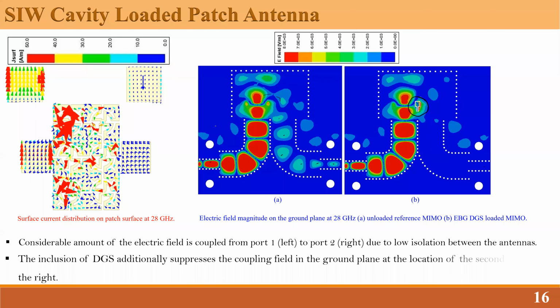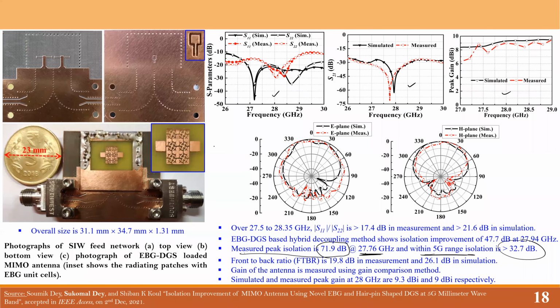A metallic waveguiding structure is basically like a metal box. You can also make waveguiding structures that behave as a waveguide on a PCB. On the PCB, you have a ground plane, a metal over here, and also a metal over here. In between, you create a metal post. Consider it as a side view. On both sides, there is also a metal post.